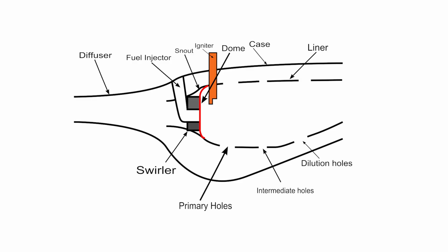It is the outer shell of the combustor, and is a fairly simple structure. The casing generally requires little maintenance. The case is protected from thermal loads by the air flowing in it, so thermal performance is of limited concern. However, the casing serves as a pressure vessel that must withstand the difference between the high pressures inside the combustor and the lower pressure outside. That mechanical load is a driving design factor in the case.